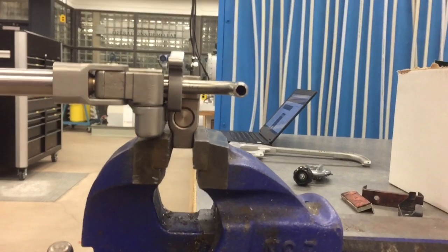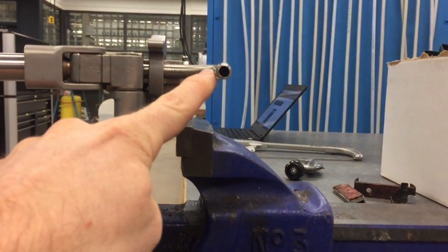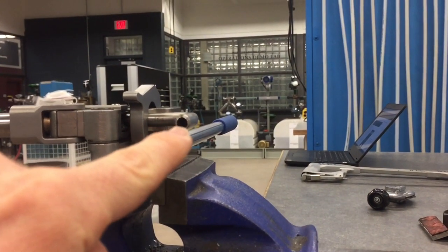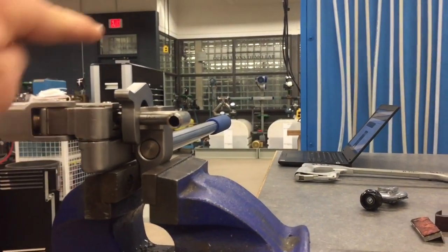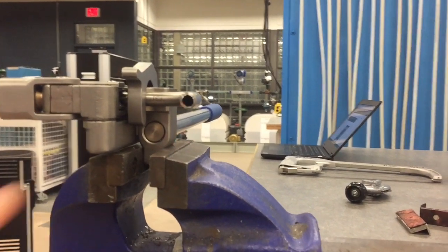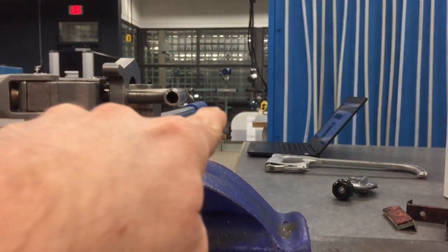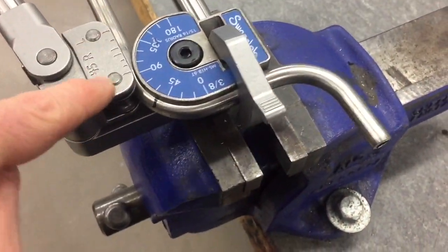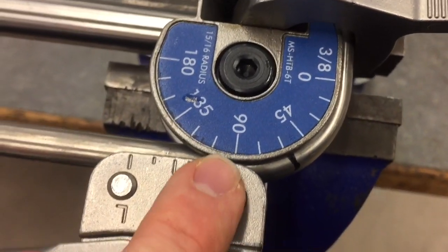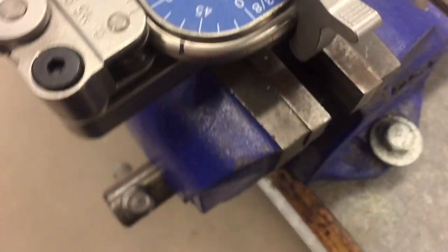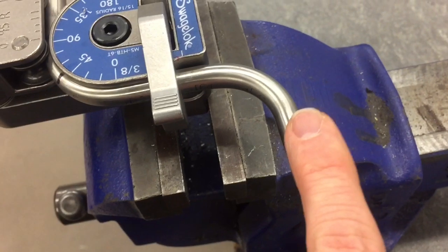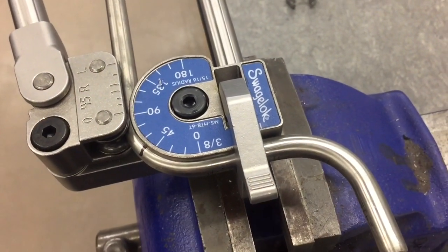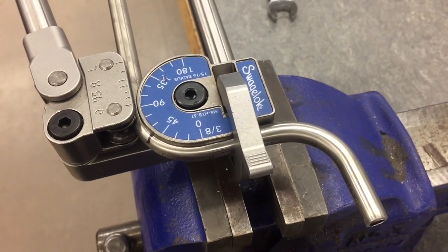Just before I make the bend, I wanted to point out that the tubing here is pretty parallel with the handle back over there. So when we do this bend, it's going to be going completely opposite of this, straight the other way, when we've completed our bend. All right, there you can see now that we've made our bend, and the 0 mark here came down to the 90 there, and now from the center of this tubing to the center of this tubing should be 3 1/8 of an inch.